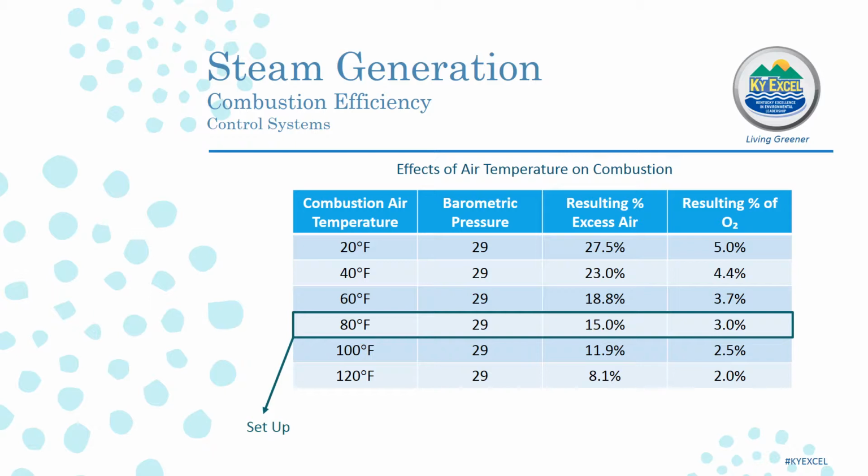soot. Soot has 5 times the insulating value of asbestos, so an eighth of an inch of soot results in a heat loss of 47%. Thus, an eighth of an inch of soot will increase fuel consumption by 8.5%. This lean setup does not replace monitoring.